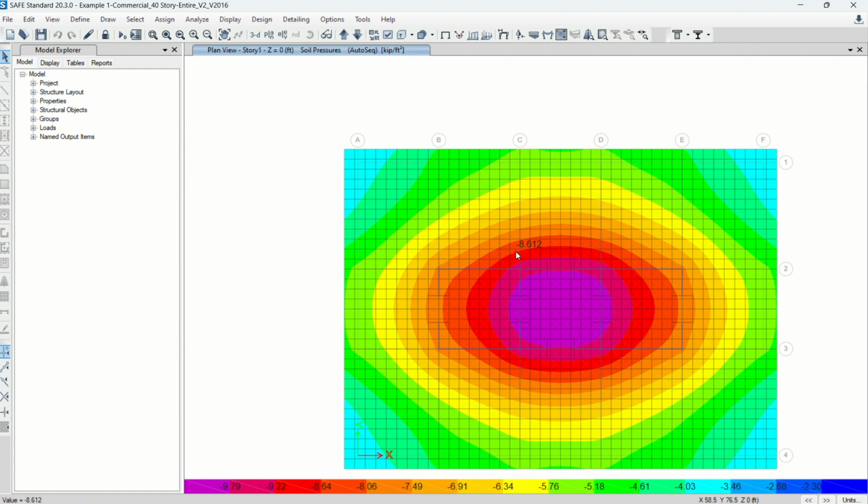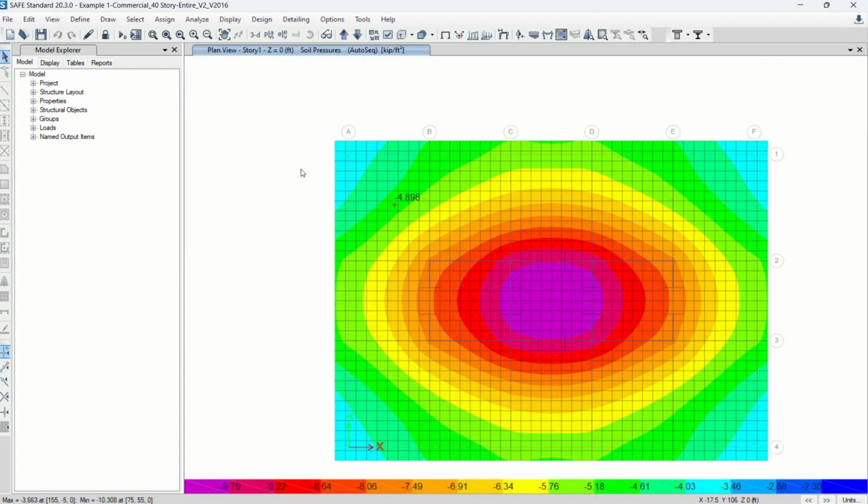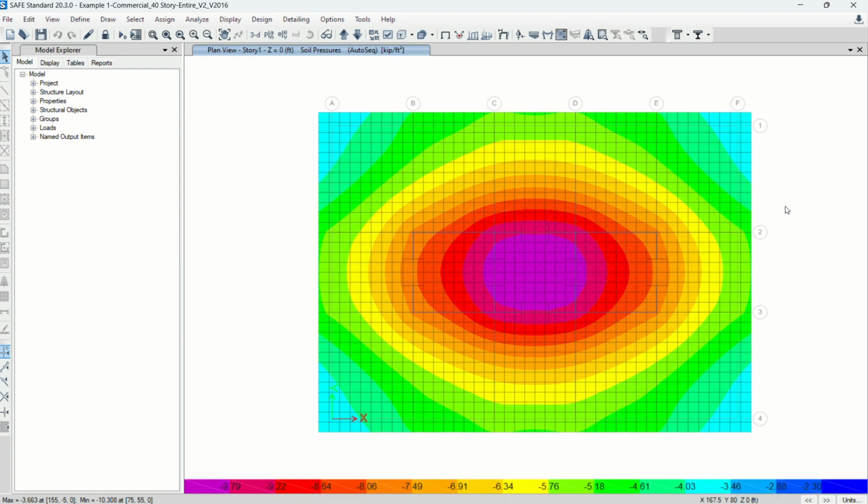Soil and mat work and perform in a similar way. If the soil is soft, it works like a soft mattress and you may experience more back pain. But if the soil is firm, the deflection is relatively more uniform, rather than a dishing effect with the highest deflection at the middle and a lower point at the ends. So it shows that this plate is going to bend more if you have a small, soft soil spring constant underneath.